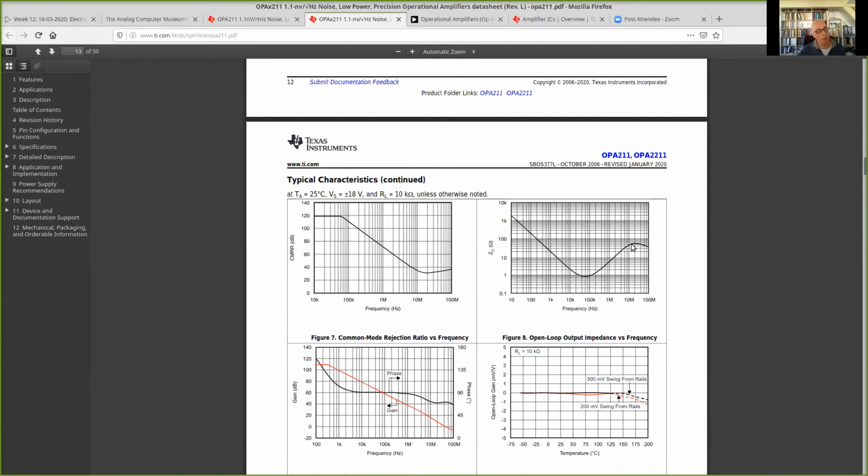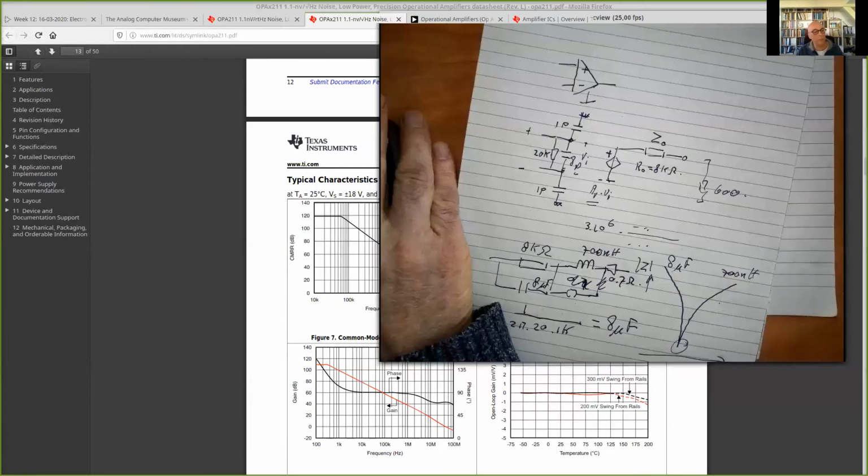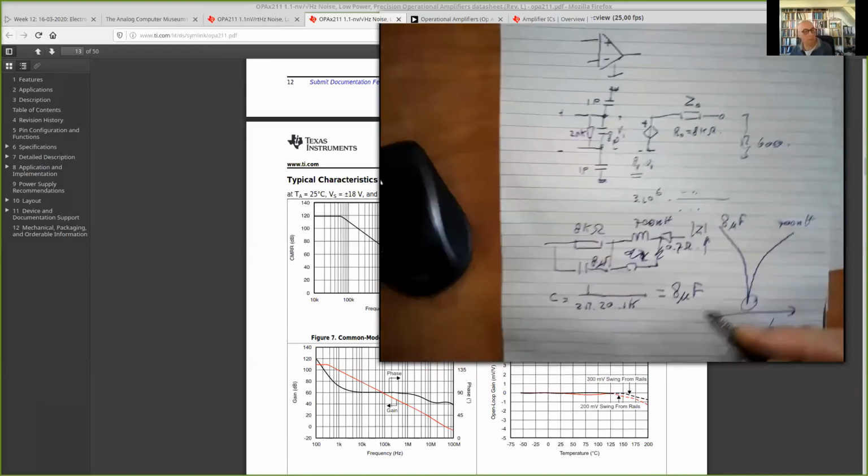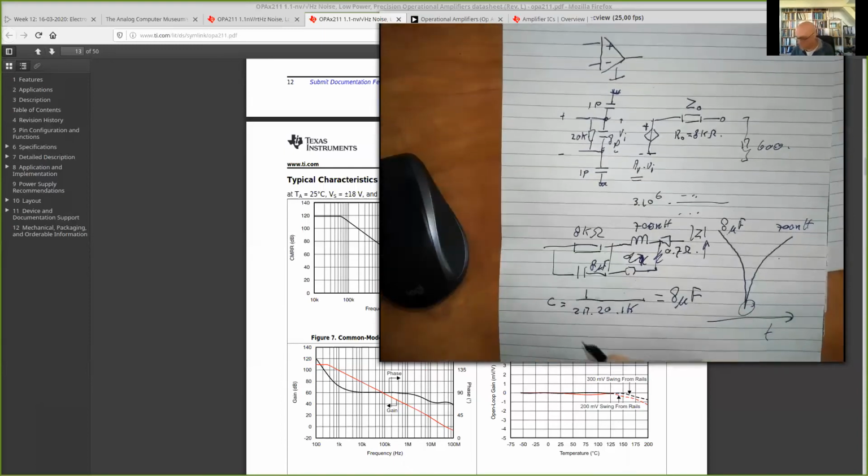And what happens here? Here it stops at about, let's say 70 ohms. So this is a resistor in parallel, and here it becomes capacitive again. So you can calculate from this the capacitor again, and then we have a complete model of the output impedance. So let's draw it again, in a little bit more clean way.